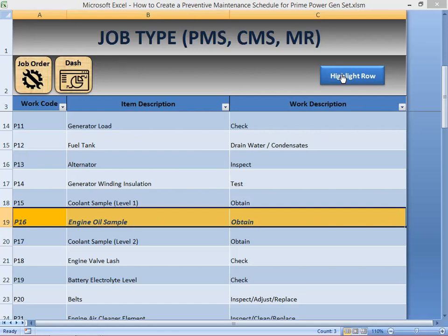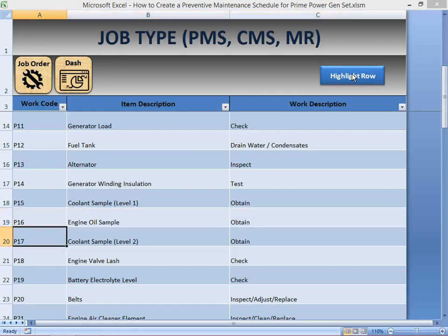If it's more than 1%, that is already bad and something is wrong with the piston ring, maybe sticky, and some blow-by is happening through the piston ring and going into the oil sump, mixing with the oil. So you need to get some samples, and that is what this job is all about.